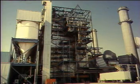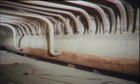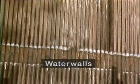From the outside, boilers look like big boxes. Some may be over 200 feet tall. This boiler is called a drum-type boiler because it has a component called a steam drum on top. The drum collects the steam made by the boiler. The walls of vertical metal tubes that line the inside of the boiler are connected to the steam drum. These tubes are frequently referred to as water walls because they're filled with water. The steam that's used to drive the turbine is produced in the water wall.